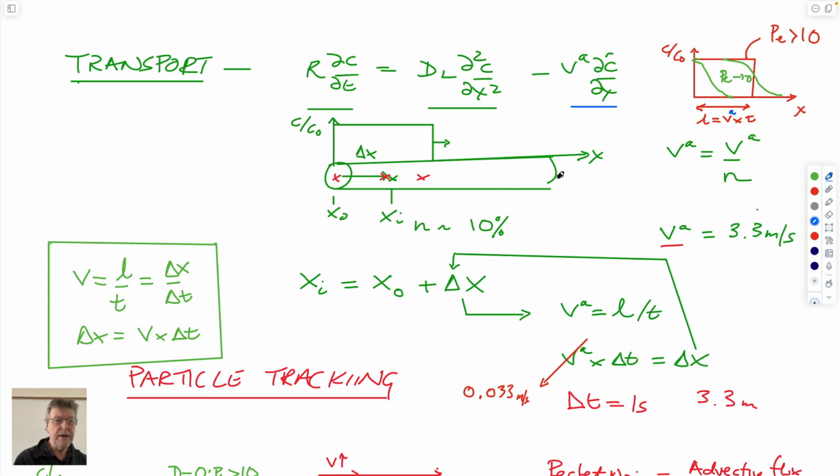You take this rather badly drawn core that we had before, from upstream to downstream. Since we know that the flow is from upstream to downstream for the water, if we entered a mass of some contaminant into it at the upstream portion, we'd have a relative concentration at the upstream boundary condition, and over time it would propagate downstream so that we'd have this curve of this pulse, clean water ahead of it, contaminated water behind it. Maybe it's canted over because of diffusion, but we're not going to worry about that.